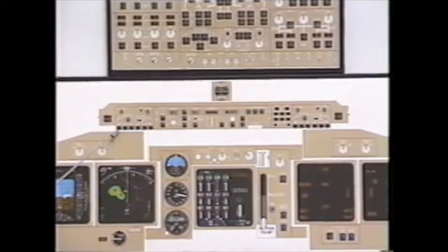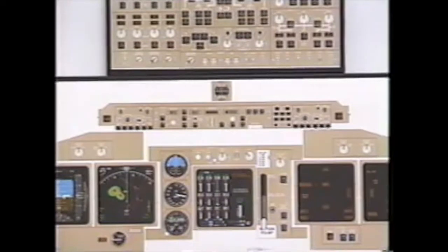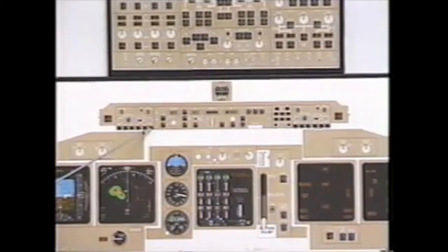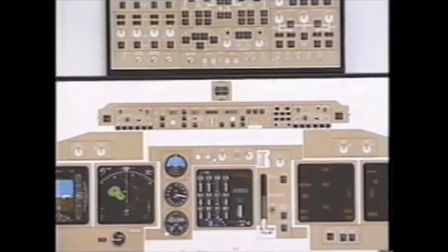Weather radar turns on the weather radar transmitter, so this is basically the weather radar on-off switch. Stations, waypoint, and airport will turn on the stations, waypoints, and airports based on range, high altitude or low altitude. That is FMC generated. That would not be raw data. To actually pull up the raw data, select position, that would be raw data azimuth and DME to the station. Data simply turns on the time on the nav display at which you'll reach certain points.